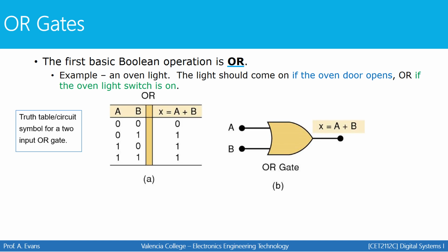When we discuss the idea of OR, we begin with the truth table, and then we begin with a symbol to sort of represent what OR stands for. So first I'm going to start by looking at the truth table. The truth table is here on the left. A truth table is a tool that we use to be able to evaluate the output of any digital circuit. On the left, you're always going to list your inputs. An OR gate could have two inputs, and we're going to call those inputs A and B. So on the left, we have input A and input B.